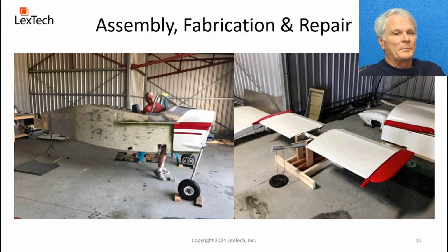Now, as I started putting the stabilizer on, you can see I was doing my Fred Flintstone imitation there on the left. You can see the counterweight on the right for the stabilizer is one of the anti-flutter and also to control the stick force. You also can see some lead weights on the tips of the stabilizer. That was also needed for flutter relief.